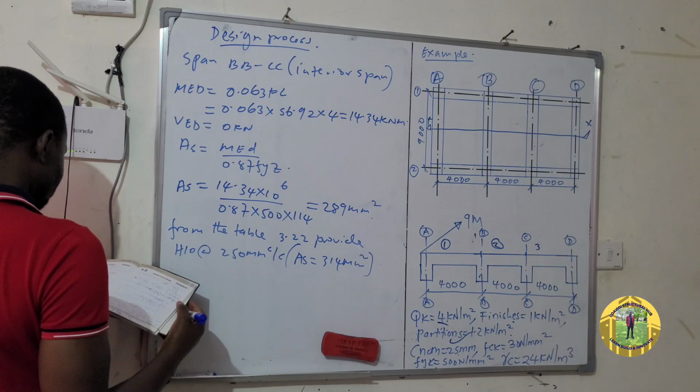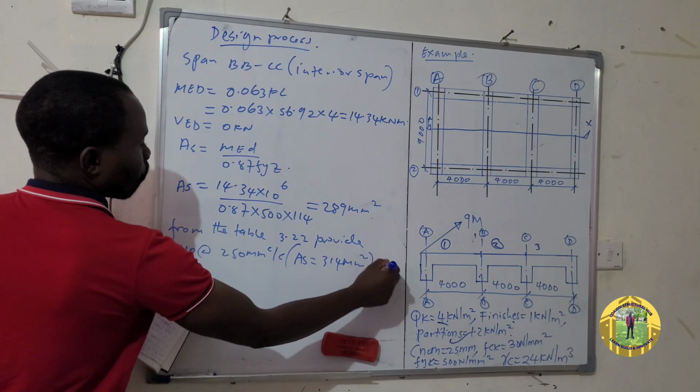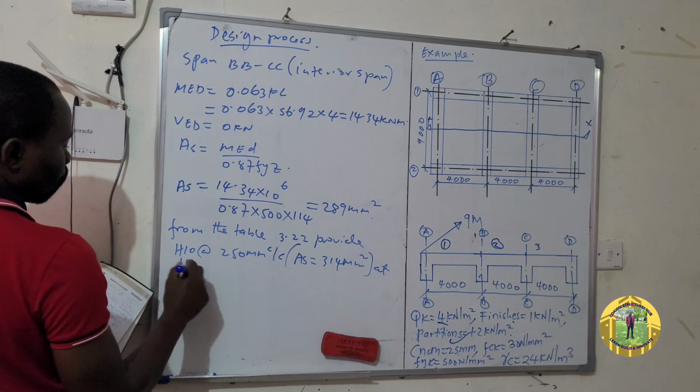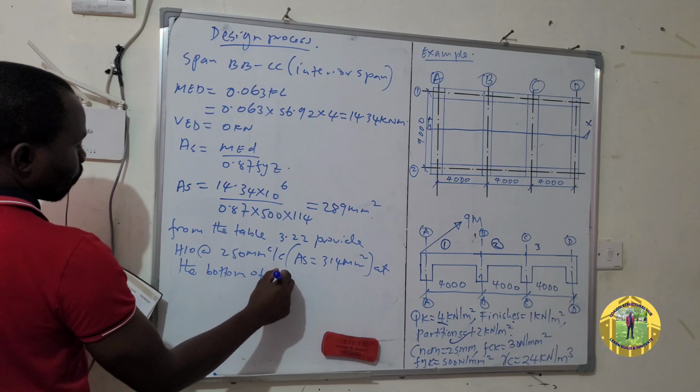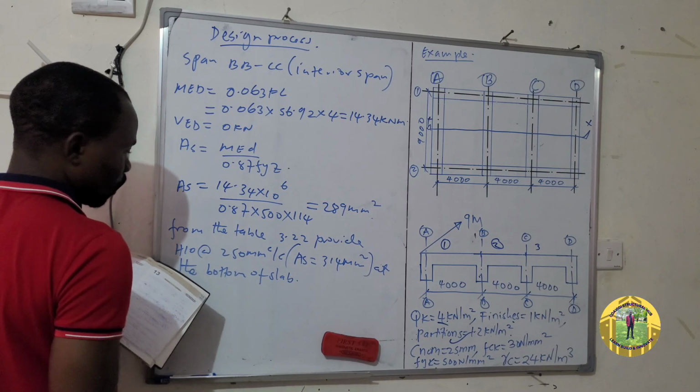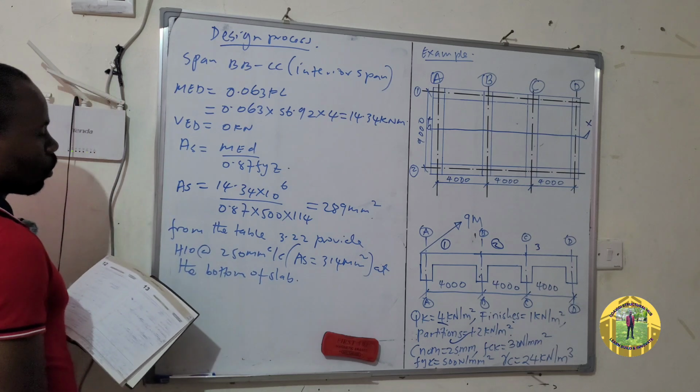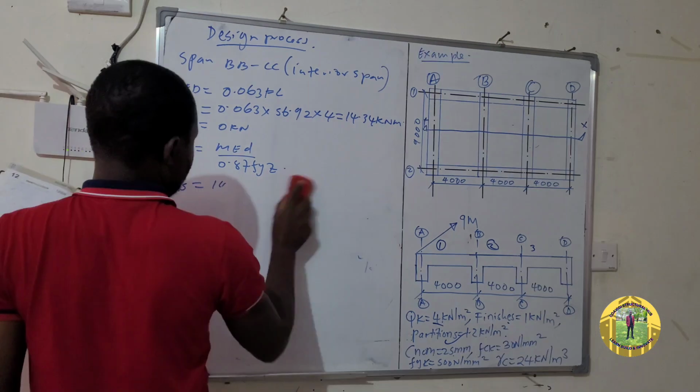This is provided at the bottom of the slab, because it has a positive design moment.